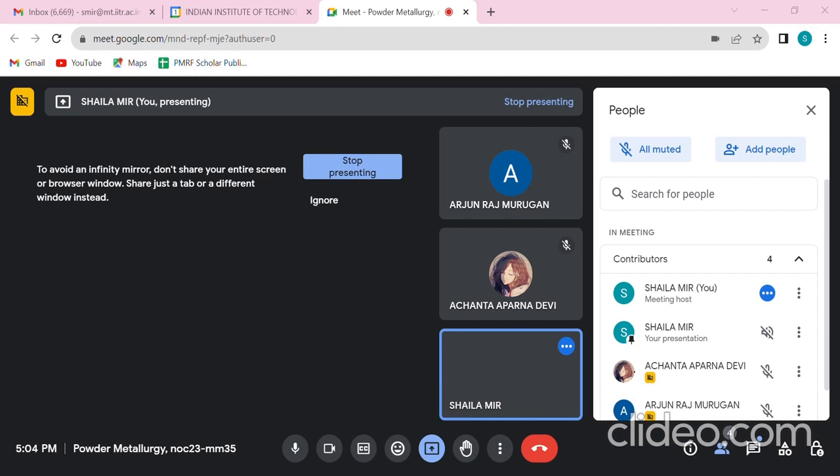As you increase the sintering temperature, the grains tend to grow. There is grain coarsening happening, and the pore is not able to move at the same speed as the grain boundary is moving. Because of that, we'll have a separation of the pore and the grain boundary, and as a result, we'll achieve a maximum density in the material. So the separation of pore and grain boundary is the right option.